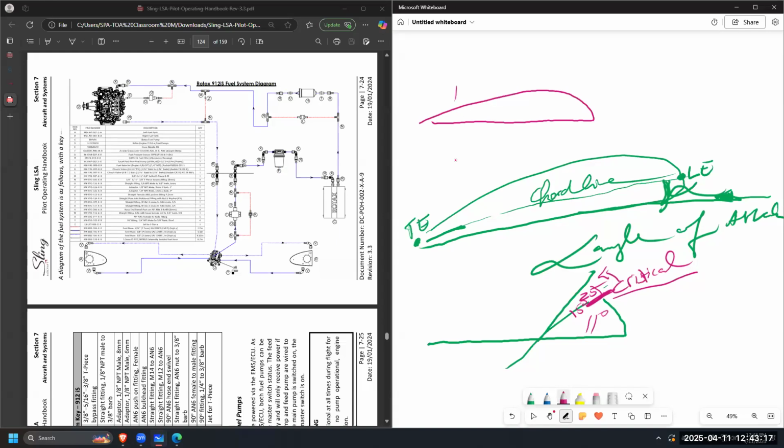as you're increasing the, this is your center of lift, right? Right here, at low angles of attack. If you're increasing the angle of attack, where does this move? Backwards or forward? It moves forward.